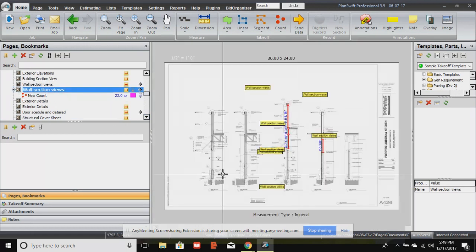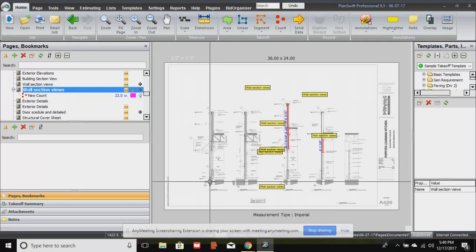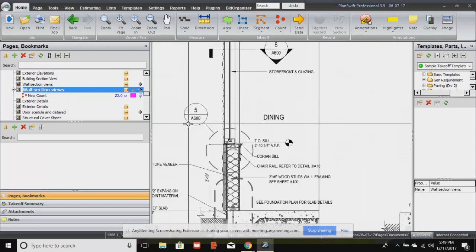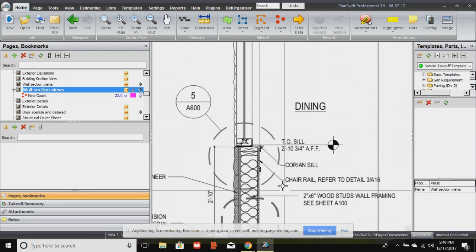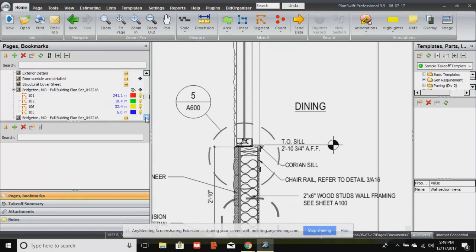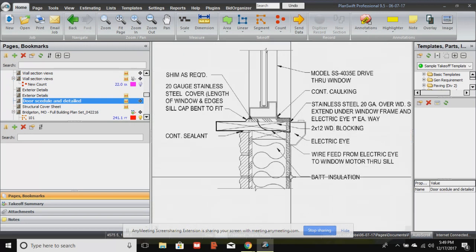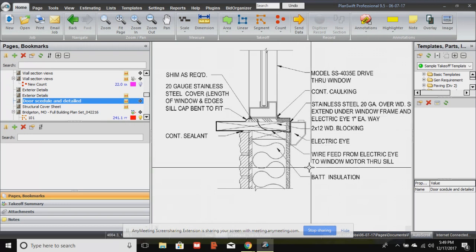Okay, section view, view of the project just at that one point in time, and so the section view sheet shows you section views of the wall at different locations. Then from our section view we went to the last of our construction views, which is a detail view. The most detailed of the views in terms of construction, and that took us there. So that's these views. We're down to the nitty-gritty. If you had to do a mock-up of that, you wouldn't have to look at any other sheets, because this is the most detail, that's why they call it a detail view.